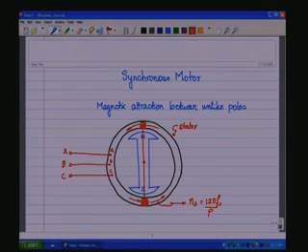What is different is the rotor. The rotor is a magnet which has north and south poles. So therefore at a given instant, let us say this portion is south, this portion is north. Let us say the field which is rotating due to the excitation of the stator is having a north and the south pole like that. The rotor is also a magnet. It has its north and south pole. So the north pole is getting attracted to the south pole of the rotating magnetic field. The south pole is going to get attracted to the north pole of the rotating magnetic field.